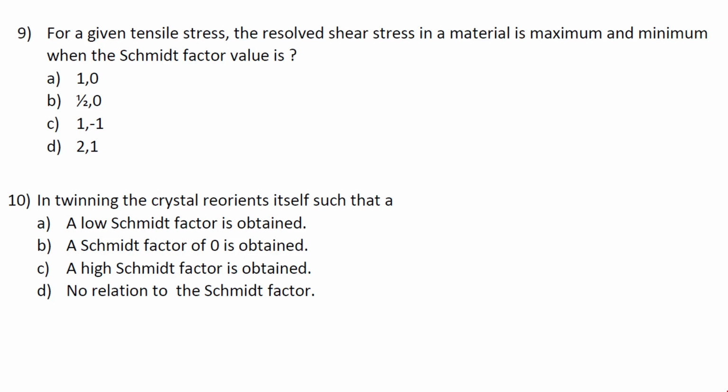No. The resolved shear stress is maximum when lambda equals phi equals 45 degrees, so that the resolved shear stress will be equal to half sigma. Half and 0. Okay.